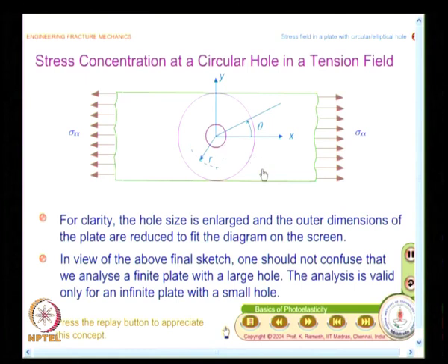And there are other things that also we do. Though the problem is like an infinite rectangular plate with a small circular hole, one of the methods of solution is to look at this as a boundary which is circular in nature at infinity, and rewrite the boundary condition. You have only sigma xx; this stress component could be rewritten as a suitable boundary condition for a circular plate.